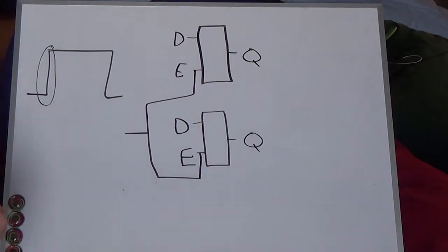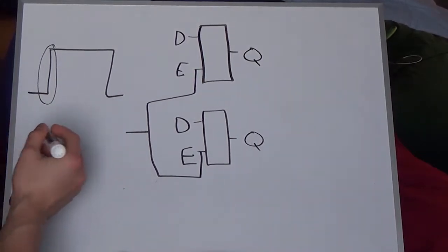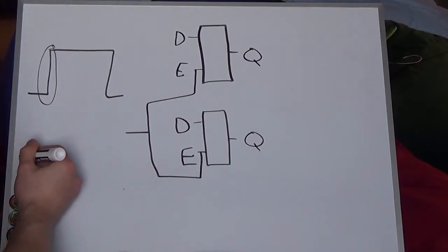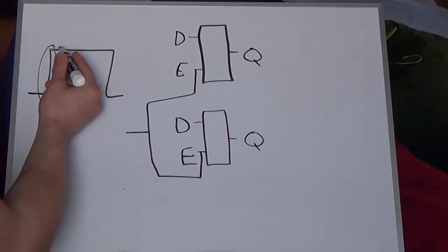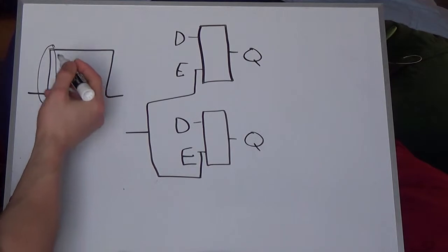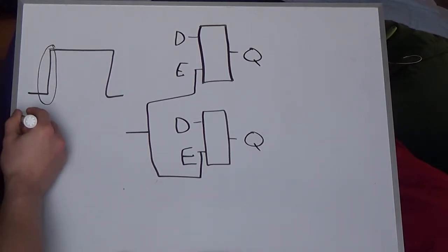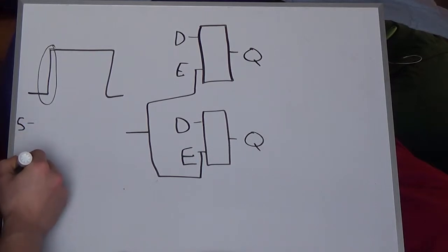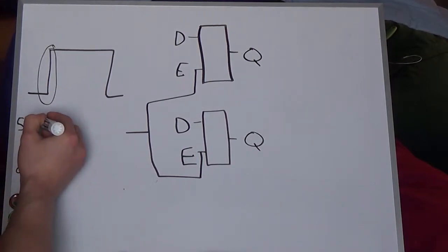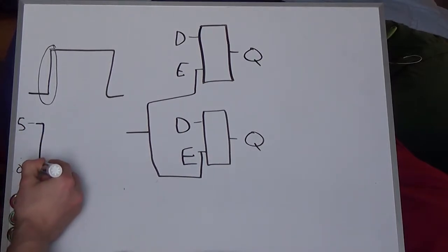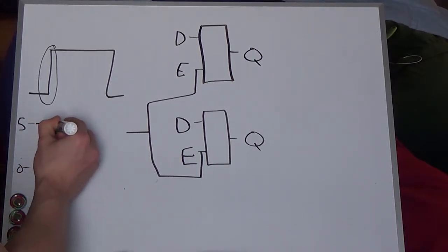So what I decided to do was to build some sort of setup built into these registers, so that instead of having a signal like this, if this is positive 5 volts, if this is 0 volts, every time the signal jumps high, this here will jump low, and then after a certain short amount of time it'll jump high again.